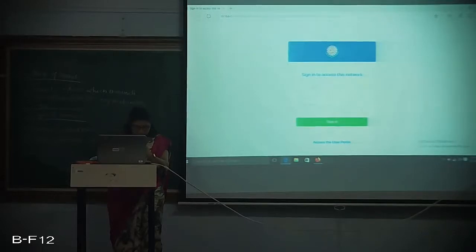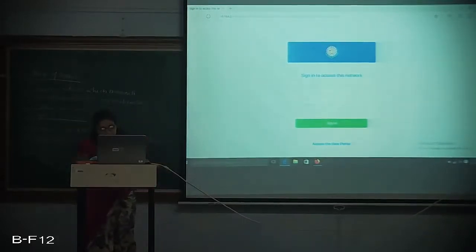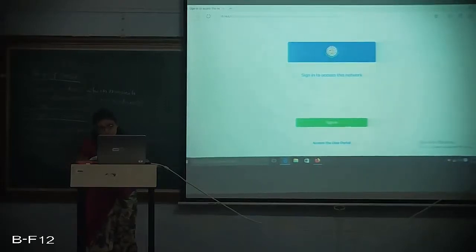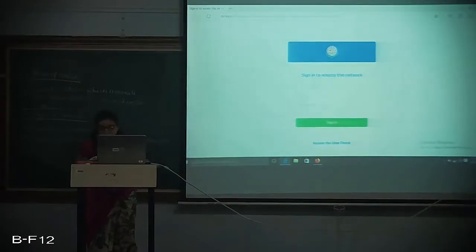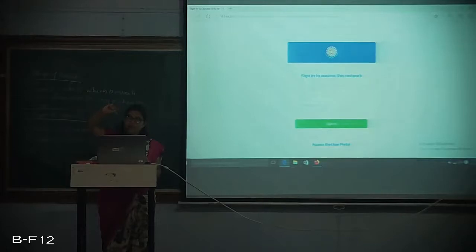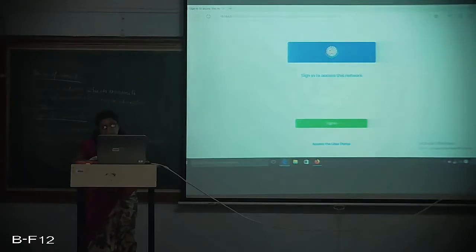Then electrical machines have push on-off buttons. Toggle switches are used when positions are fewer in number, whereas rotary switches are employed when there are more. Toggle switches are used for two positions, one for on and one for off. Unlike the toggle switch, rotary switches can have 24 positions. For each position there should preferably be an audible click. We can hear some sound while moving it, so we can easily understand we have switched and increased the speed by one step, two steps or three steps. Again, it depends.